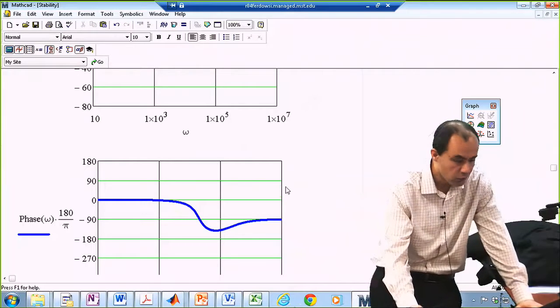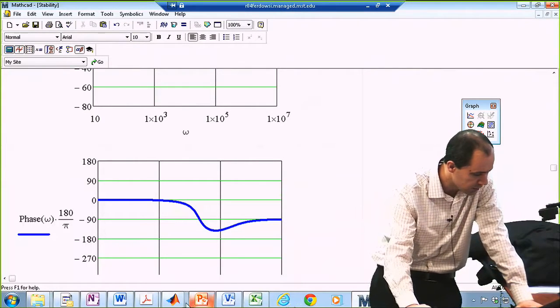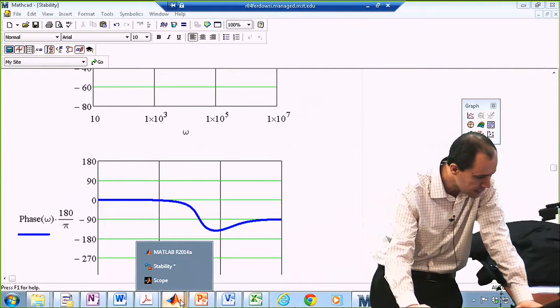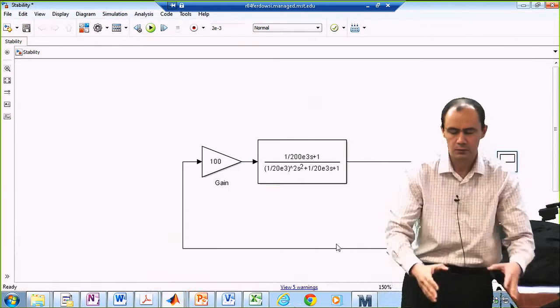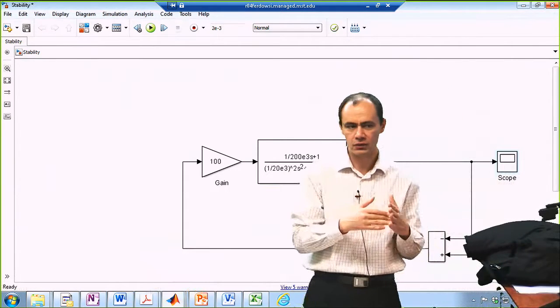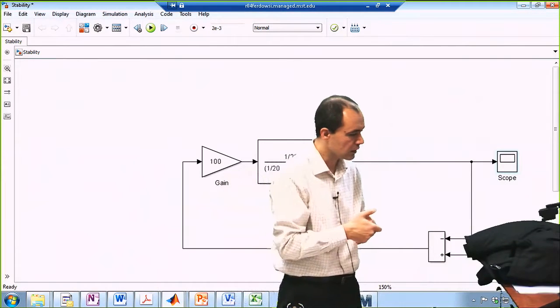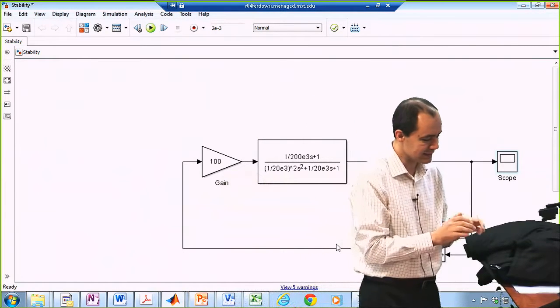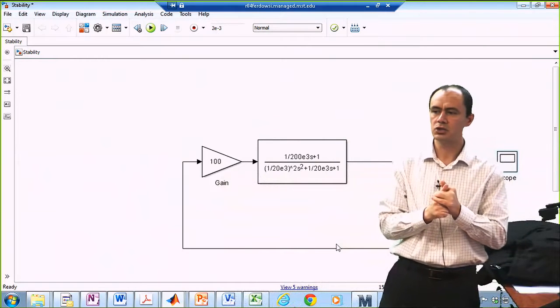You can increase the gain and go crazy. But this is not what you usually do in a real system, because real systems are a little bit more complicated than this. And you may start wondering, in order to eliminate this steady state error, you can never eliminate it just by increasing the gain. You can just make it smaller and smaller. In order to eliminate this steady state error, you always need to have an integration block.